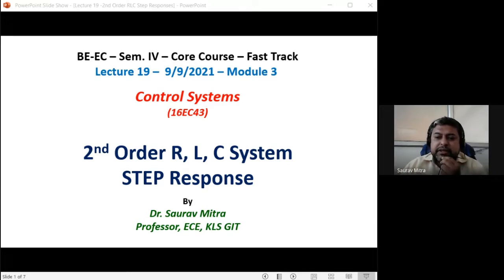Those cases we will see when we study steady state response. We have given 1 volt input to the RC circuit. Ideally it should be 1 volt across the capacitor, but sometimes it might not be. Suppose the output is 0.8 volt. Then 1 volt is the input, and 0.8 volt is the steady state output, not a transient. So 1 minus 0.8, that is 0.2 volt, will be the steady state error.